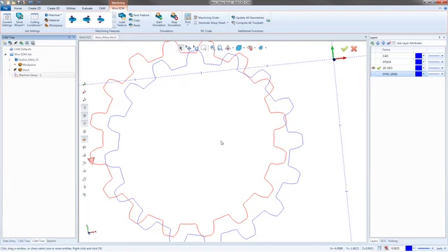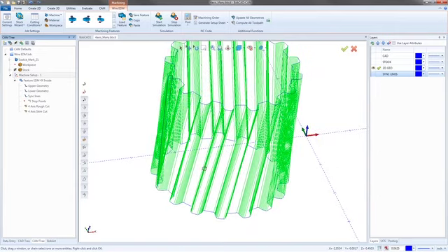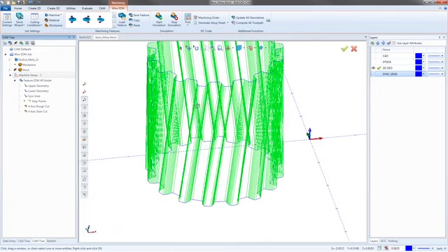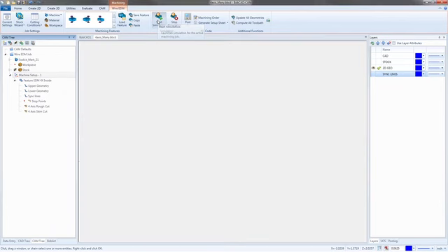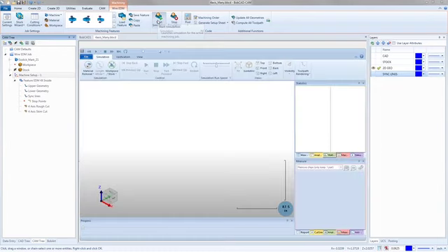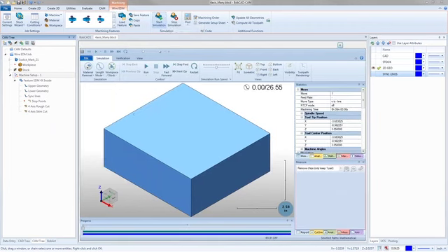So hopefully it computes. There we go. That looks better. So pretty much what it does now is it uses all those exact lines that I created, or that I pulled from the model, which is pretty well what I would have used to create the model in the first place, because this is all custom surfacing anyway. Unless you made it and then subtracted it. But I'm going to go ahead and launch the simulation. So I have it lined up the way I want it. Origin looks good. A really big part of this is getting your start points right, because BobCAD will create this toolpath, and a lot of times it even looks fine until you actually see how it's cutting.